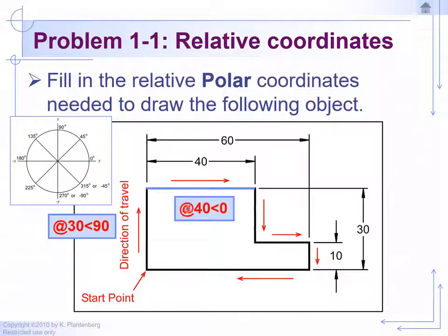Make sure you type in @40, and to access the less than symbol, you type on the keyboard Shift, comma, 0, and enter, and that'll generate the line.